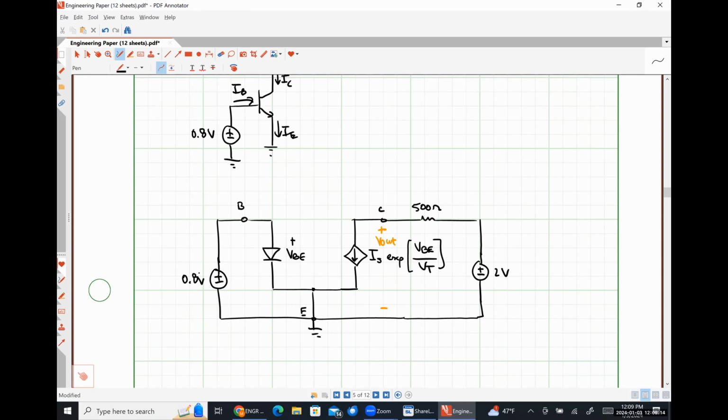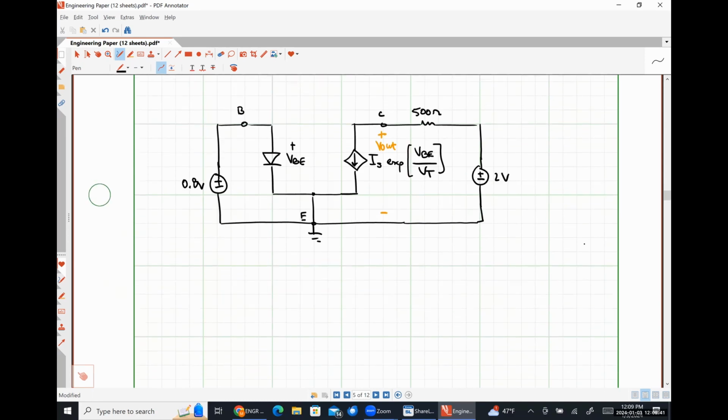All right. So hopefully figuring out what all of our currents are is going to be a joke right now because we don't even need the model for that at all. We have an equation, right? Our collector current is just IS times EXP of VBE over VT. We know what IS is, we know what VBE is. Let's assume that VT is 26 millivolts because they're operating at room temperature. So IC is going to be 5 times 10 to the negative 17 amps times EXP of 0.8 volts over 0.026 volts, which comes out to be 1.153 milliamps.